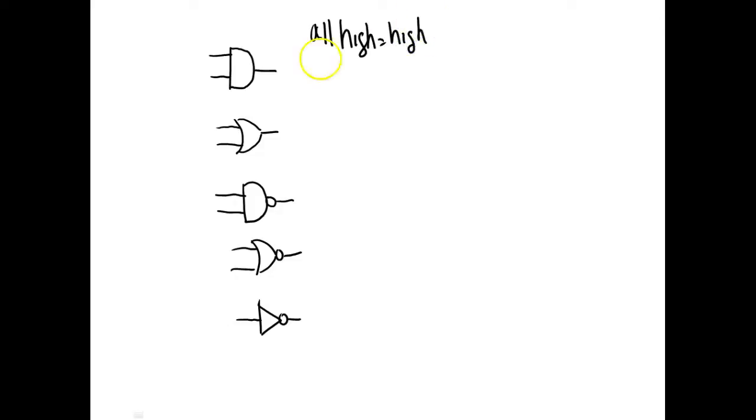So we come up here and develop a truth table, and this is why we're going to do this, because it's so easy to do it with 2 inputs, right? Because we know that the truth table varies with 2 to the power of the inputs, right? So if we call the inputs A and B, and then we call the output X, then we know it's 2 inputs, so all we do is start counting in binary.